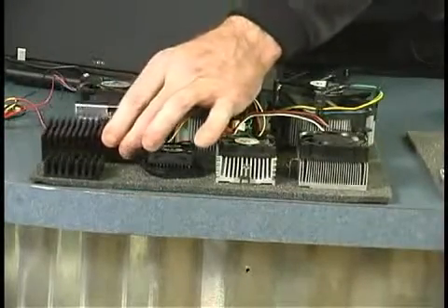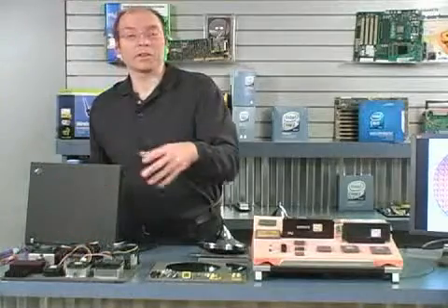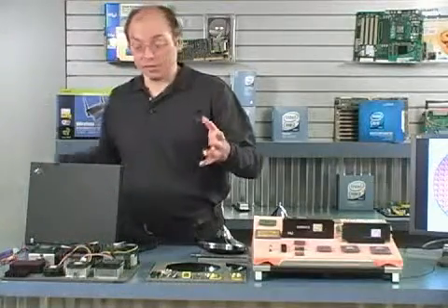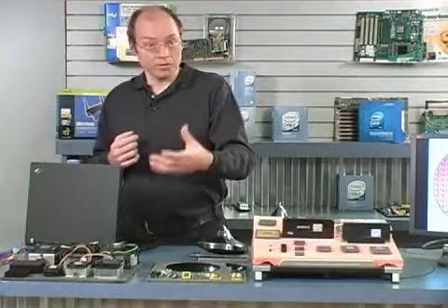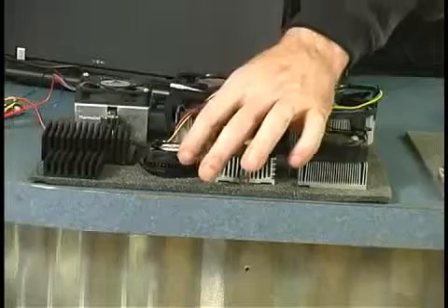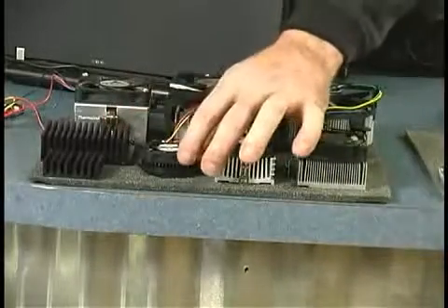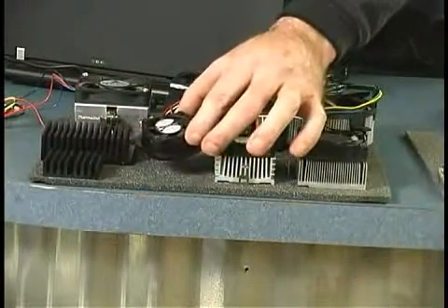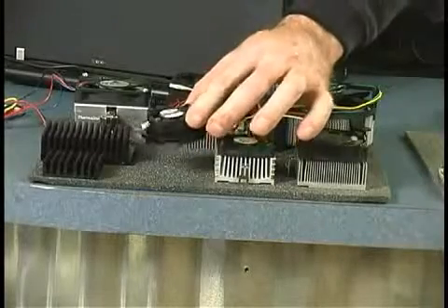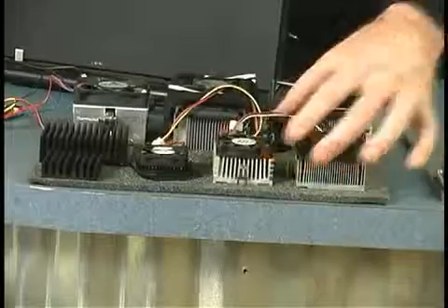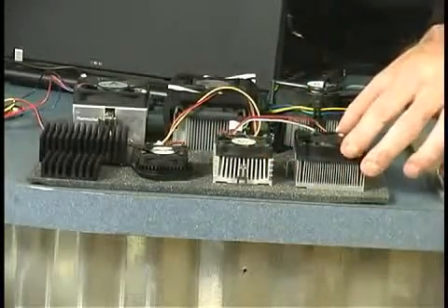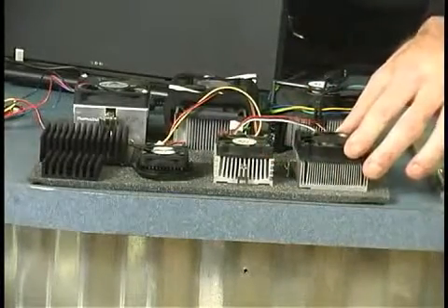But when we went past 233, we found that the airflow in the system wasn't sufficient. You either need a really large metal heat sink, or you could use a smaller one and put a fan on it. So instead of having something big like this, we had something smaller, but it had a fan on it. So this was around a 200 to 300 megahertz processor cooler. As we went up to 400 and 500 megahertz, the processor coolers got bigger, and the fans got bigger.